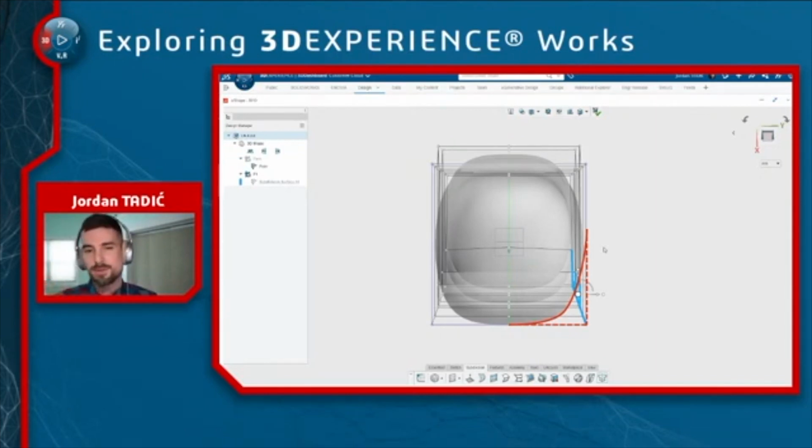But here I'm just bringing it up because it gives you an understanding of what the cage is doing. So what a 2D style spline is to a 2D sketch, the cage is to this entire 3D surface. It's like 1,000 style splines surrounding the model and transposing the entire model. And you can tweak any one of these cage points just like you could tweak a style spline to influence the shape in that particular region.